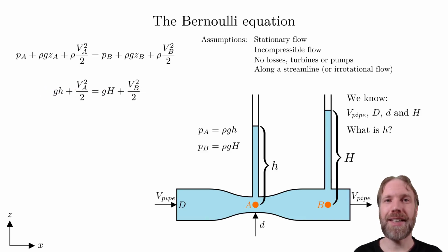We need one additional equation to determine the relationship between VA and VB. For this, we can use the continuity equation for pipe flow. In this problem, we will assume constant flow over each cross-section. Hence, we can drop the average. Bernoulli requires incompressible flow, so we assume equal density.